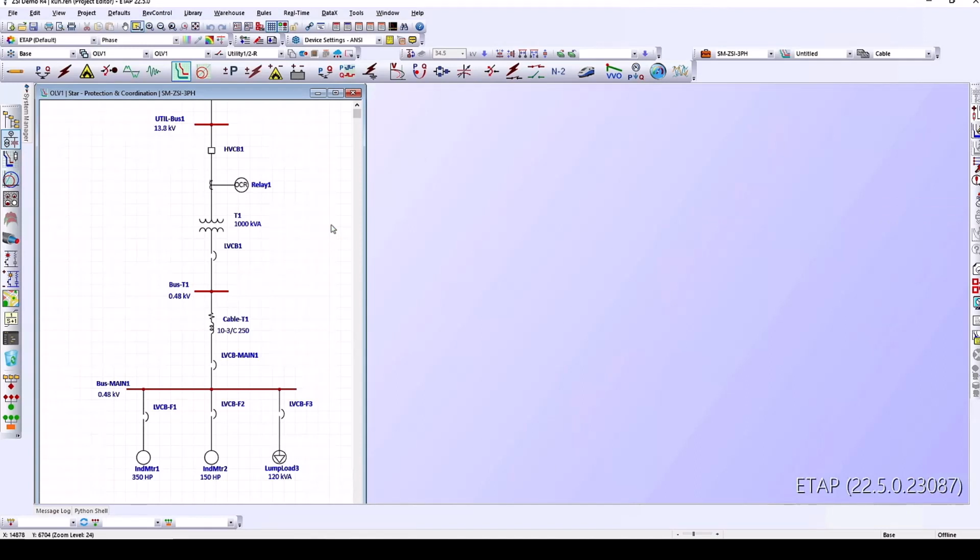Now let's take a look at ETAP, and how we can display the graphic interlocks for ZSI scheme implementation. Now we have this project open. We have base revision and ZSI revision. In base revision, we don't have ZSI settings. We don't have ZSI wiring implemented. However, in ZSI revision, we have the ZSI model selected and the wiring is predefined. Now let's see how we can enable and see how the wiring scheme is implemented.